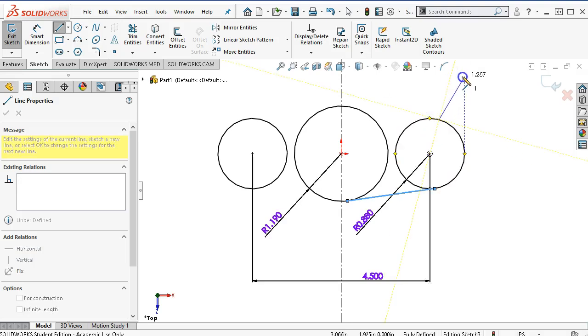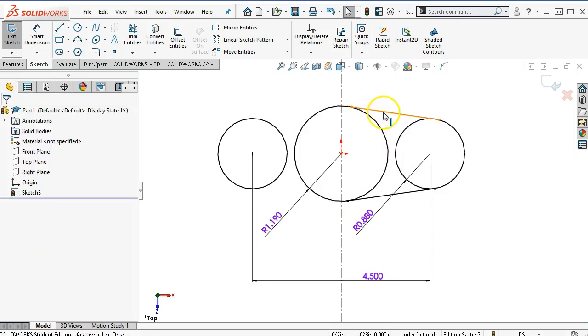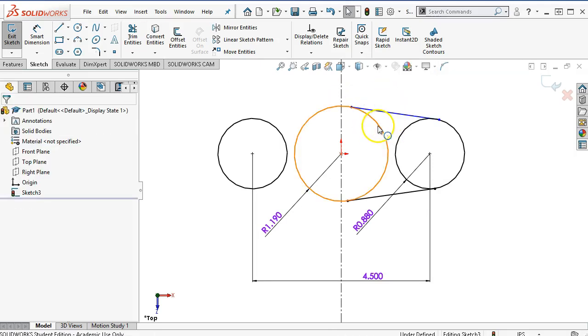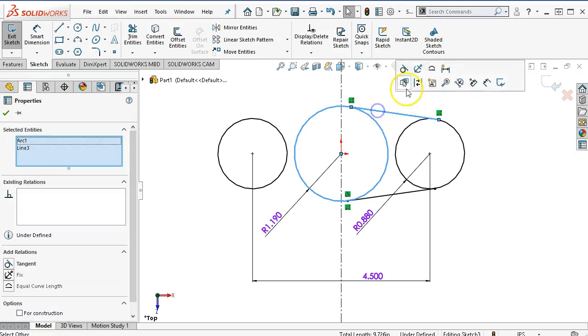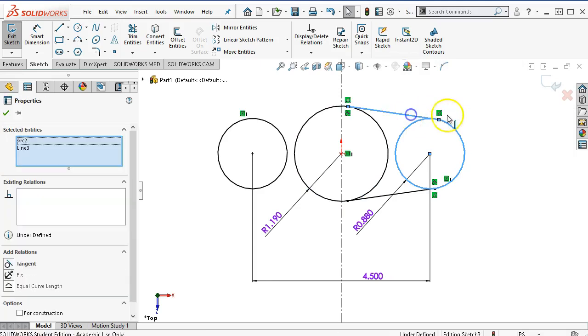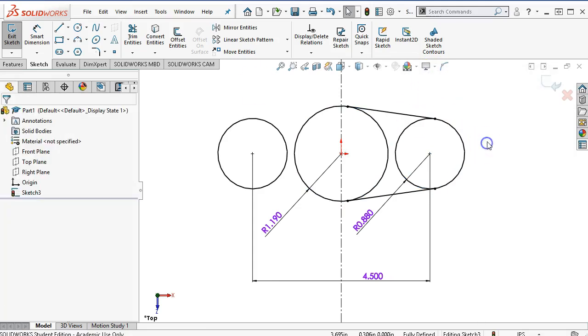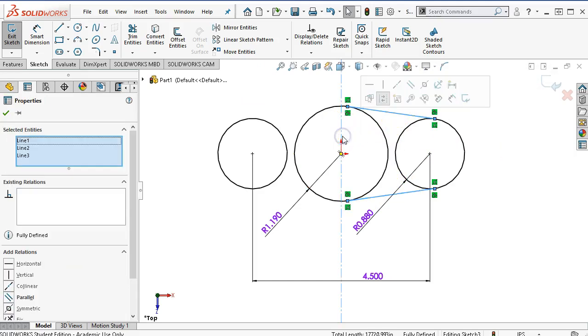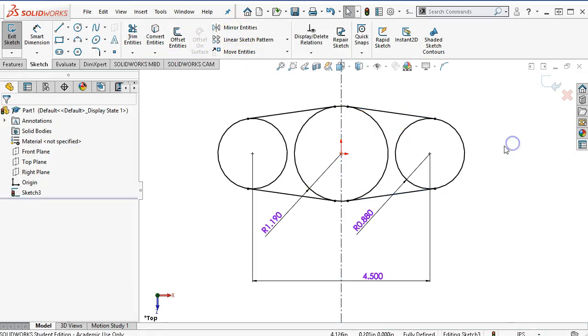Now if I drag away, notice I'm getting a standard line, and I'll bring it over and make it coincident to the other circle. And when I highlight that, I have the two coincidences, but I did not get tangency. So select, Control, Select, and make tangent. Select the circle, Control, Select, make tangent. All right, so those two. And we could have done the circles first, or connected everything first and then mirrored. But that gives me the geometry.